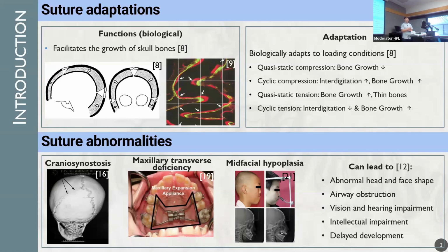Okay, well, I like that possible answer. Maybe I can suggest one myself, which is, first I thought it was weird to see a gradient, spatial gradient, because normally in mechanics, when I see that sort of thing, I see a Laplacian with a double gradient. But then, well, here's what I'm thinking. I think of everything as being like the heat equation. Yeah. Where you have change in time is proportional to basically a double gradient of velocity. And that's just saying that you want to smooth stuff out.